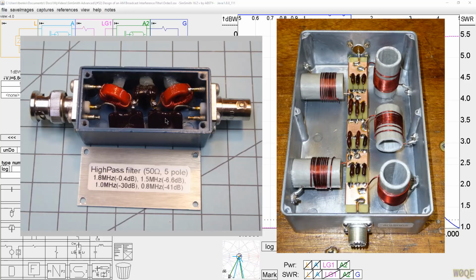These were standard values, and I adjusted the filter to meet a standard value. And that's another thing you can do if you have a few dB to spare. This filter right here represents the next filter we're going to do. It's something I built a few years ago for a guy who had a very good antenna site, with line of sight view to a lot of different radio stations. He had huge intermod problems.